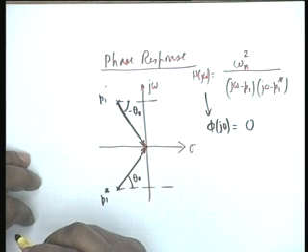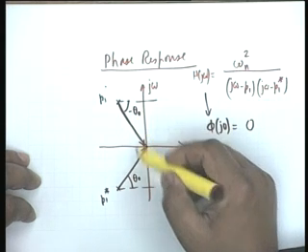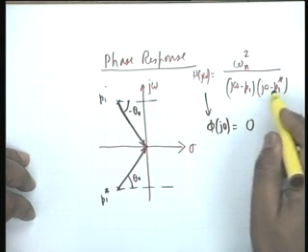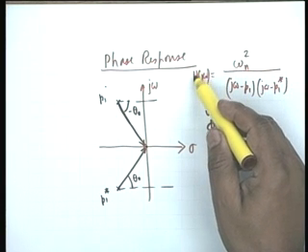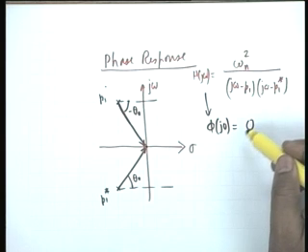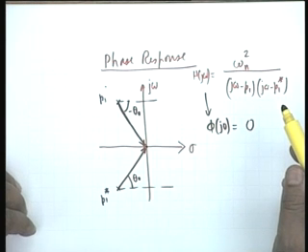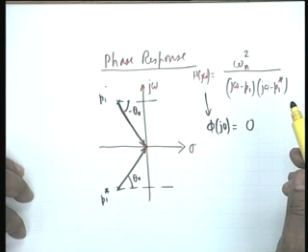You see, actually these are angles of the denominator factors. So when they go to the numerator, to make up the phase of H of j omega, you have to take them with a negative sign. Minus 0 is the same as 0. Here we are considering always the phase to be in the range minus pi to pi or 0 to 2 pi.